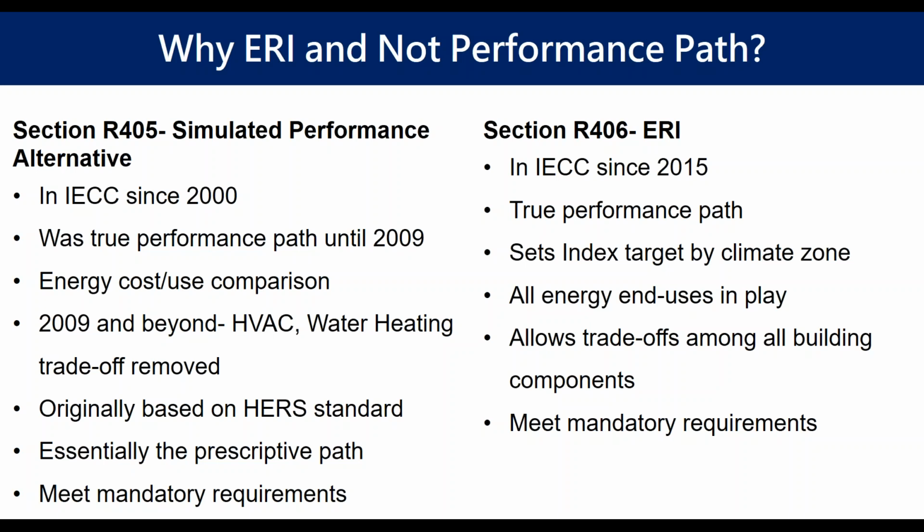So then jump forward to the 2015 IECC, where the ERI is now an option, and you're getting back to what we call a true performance path. The ERI simply sets a target score that builders need to achieve. It accounts for high efficiency equipment. It incorporates almost every energy end use within the home. So that's one reason that I think the ERI is going to see more uptake than the simulated performance alternative ever did.